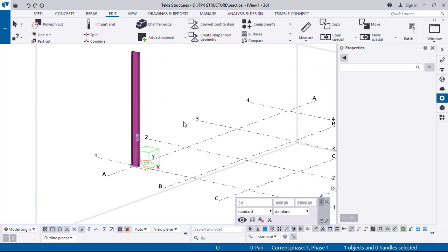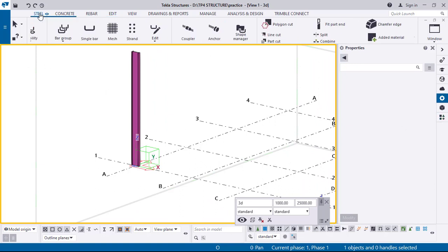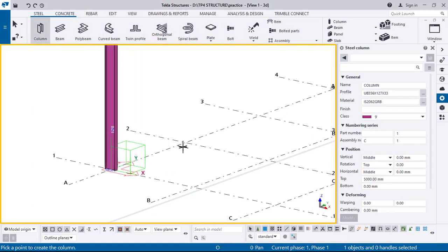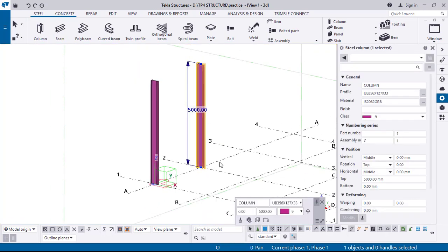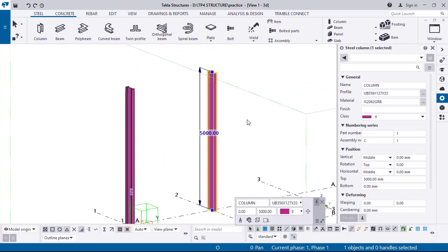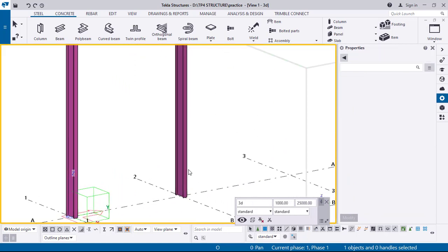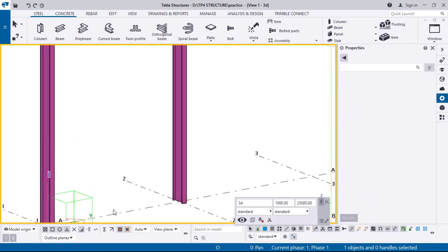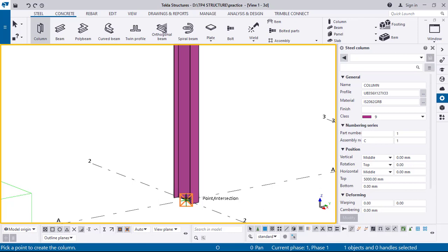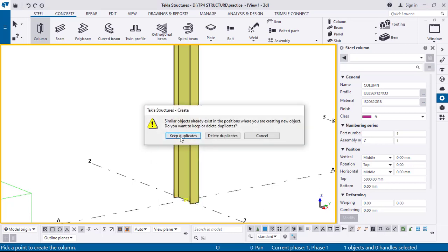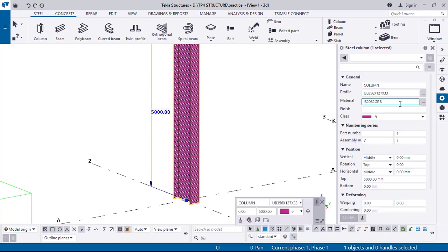then the process is the same, but we need to add some extra columns along with the same column. Suppose we are creating one column in the vertical direction, and we also add one more column here with the same point. Then click on the same point, keep duplicate, select any of the columns,